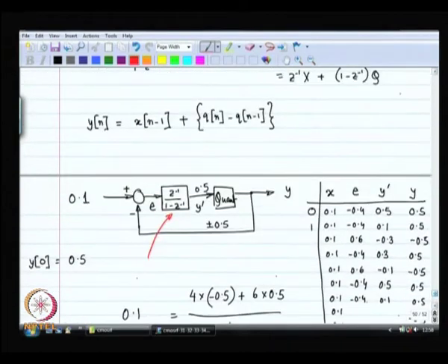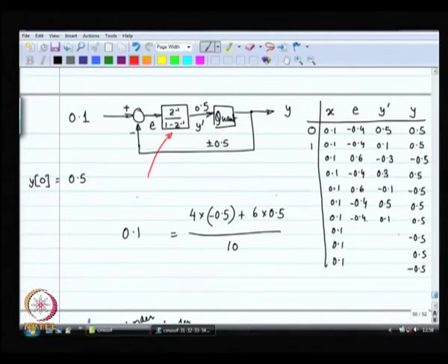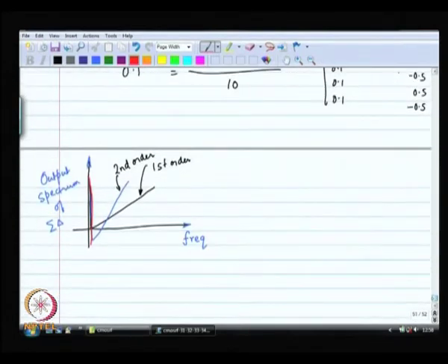Okay. So, the sigma delta modulator to use is not something very fancy. An ordinary second order sigma delta modulator will do the job for you. All you have to now make sure is that you have broken the periodicity, which second order, or if you go to a third order even better, will definitely break for you.